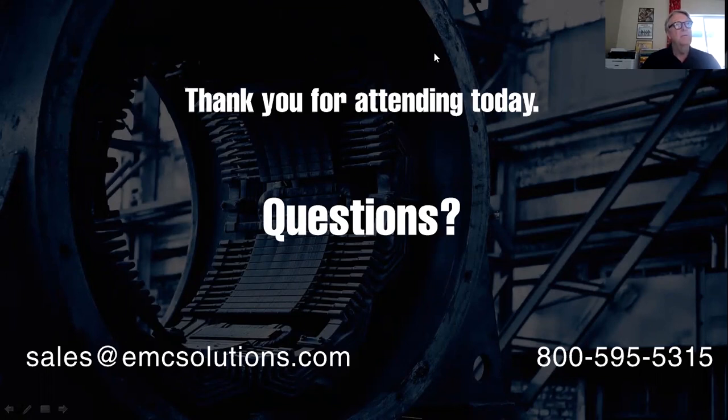And people who make passive filters, people who make the matrix inverters, which we haven't talked about, 12 pulse, 18 pulse, all of these people would generally try to tell you that you can get to 5%. But if you try to actually get there and go out and measure it in the field, you'll find out you don't get there. And none of them are willing to guarantee that. They're only willing to put that in their brochures. So in general, I personally try to get to 12% because that's what you need.